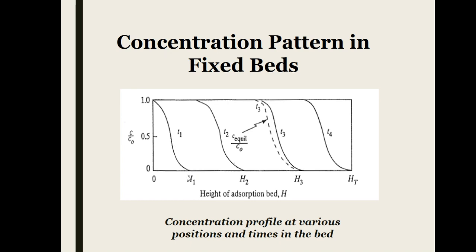Now after some time, the solid in this part is already saturated and exhausted, so there won't be any uptake anymore of the solute here by the adsorbent. It will happen on the next batch of solid and then the next and next, following the same pattern of decrease in the ratio value of C and C0.